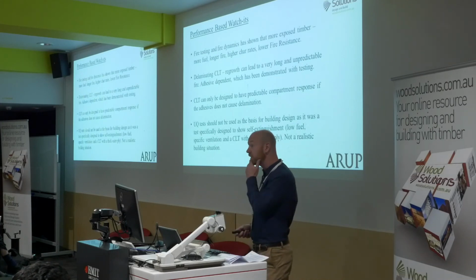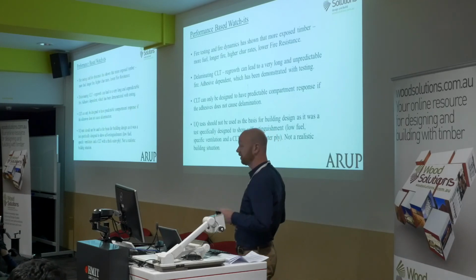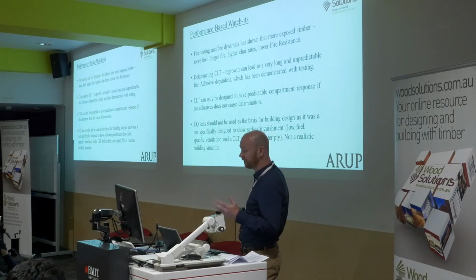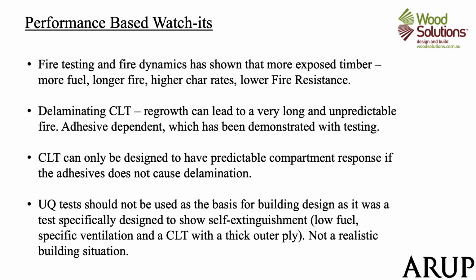Some performance-based watch-outs. So this is basically for other fire engineers or approval authorities or anybody that's involved in a design team for an exposed timber building. So fire testing and fire dynamics have shown that the more exposed timber there is, the more fuel, the longer the fire, the higher the char rates, and the higher the fire resistance required.